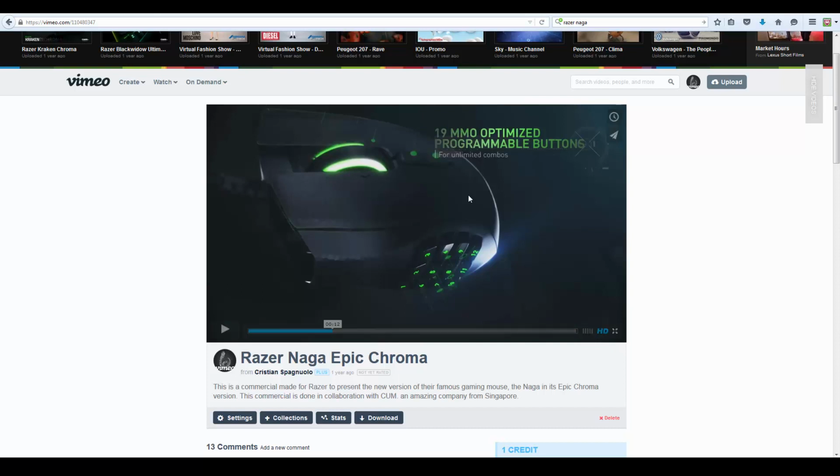But most of the time, to develop special effects like this one, you need to have a poly model of the product. So I've remodeled the entire mouse except for a couple of parts inside. All the gauges, buttons, and things like that are entirely remodeled, using a combination of Maya, 3ds Max and TopoGun. TopoGun for the base mesh, so I can remodel the topology on top of the CAD data, and then I went inside 3ds Max to do some other parts of the model.